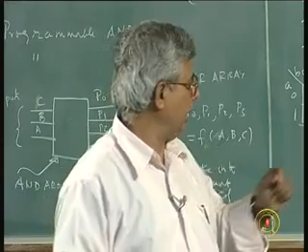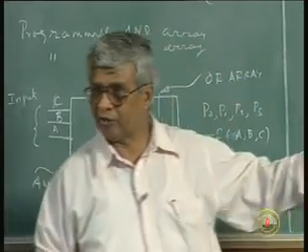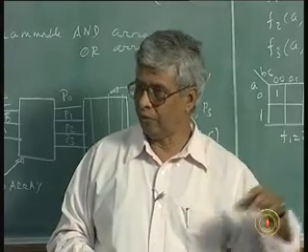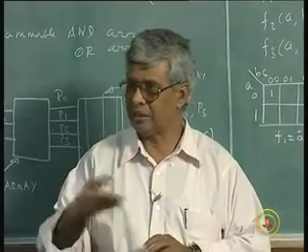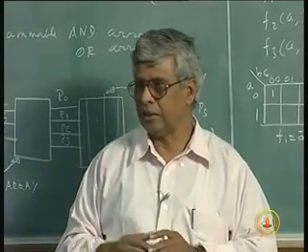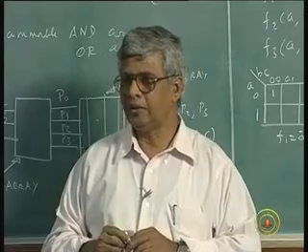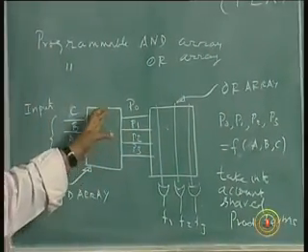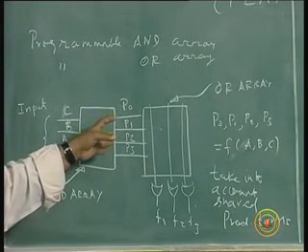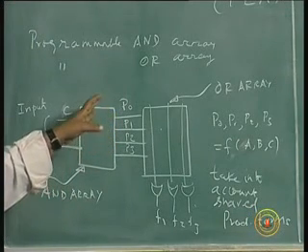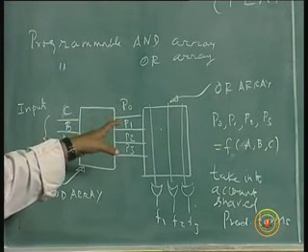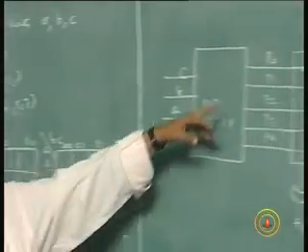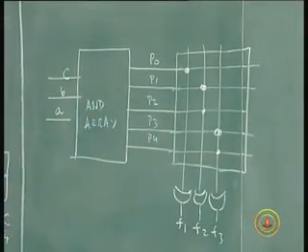Here it is not 2 power 3. It is 5 product terms times 3. So the size in bits is smaller here, and the decoder, which does the min term combination from the AND array, is also smaller now, because it requires only 5 terms rather than 8 terms with varying sizes and gates.